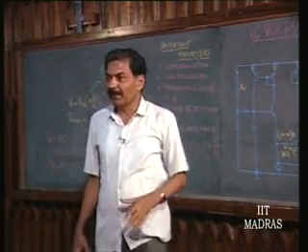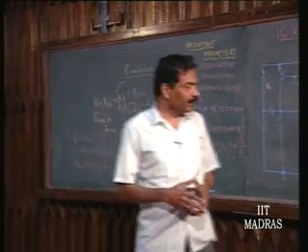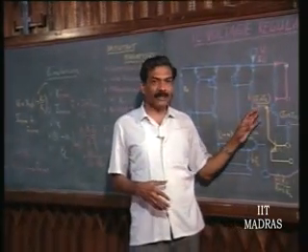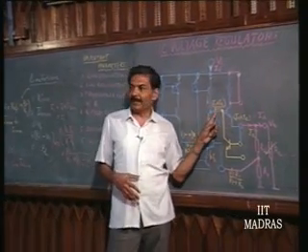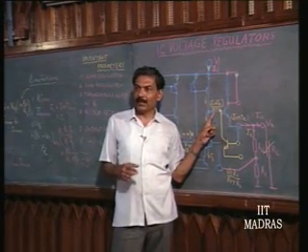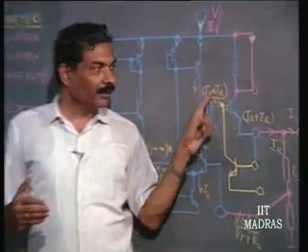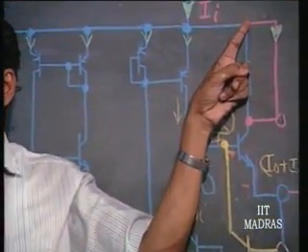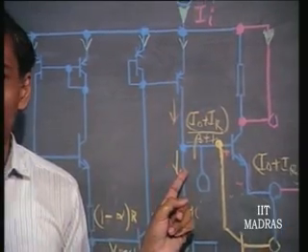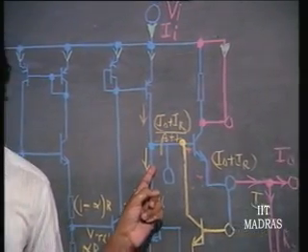Breakdown. What is going to break down? Now obviously, the collector base voltage will keep on increasing. This voltage is remaining constant. What is it? It is V naught plus V gamma. And this voltage is going on increasing. This collector base breakdown voltage is the limitation on that.